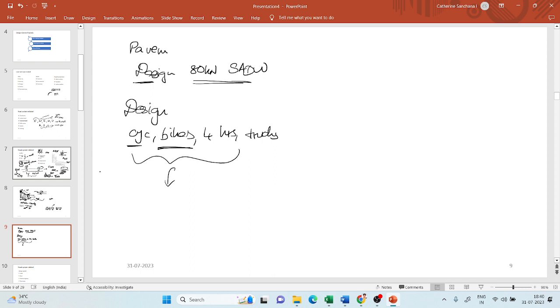But if you take each of them separately, it is going to create a confusion, or maybe not even feasible. So, in order to make it simpler, you convert the different classes of vehicles, this heterogeneous traffic, into one standard vehicle. Okay, and that is the passenger car.